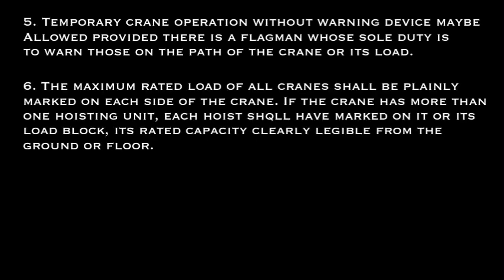The maximum rated load of all cranes shall be plainly marked on each side of the crane. If the crane has more than one hoisting unit, each hoist shall have marked on it or its load block its rated capacity clearly legible from the ground or floor.